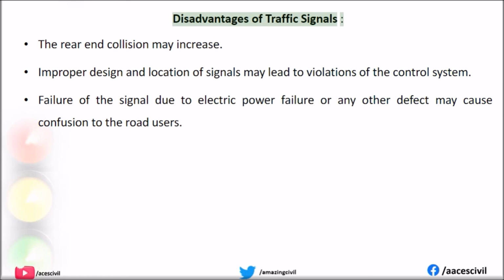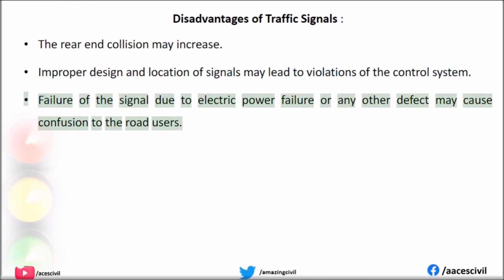Disadvantages of traffic signals. The rear-end collision may increase. Improper design and location of signals may lead to violations of the control system. Failure of the signal due to electric power failure or any other defect may cause confusion to the road users.